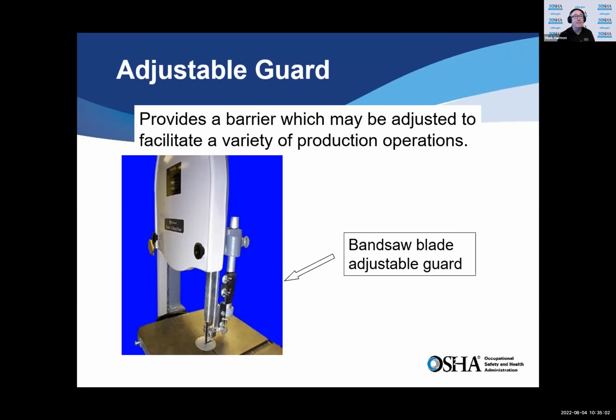That's maybe not good. If the guard's made out of plexiglass, okay, yeah, plexiglass can be thick enough, hard enough. You can see through it. That's a good thing. But don't make guards out of cardboard. Believe it or not, I had the occasion somebody put a guard on that was made out of cardboard, and I went, okay, yeah, no, that's not. I don't like that one because to me, it'd be easy to defeat that, right? Somebody just tear the cardboard off.